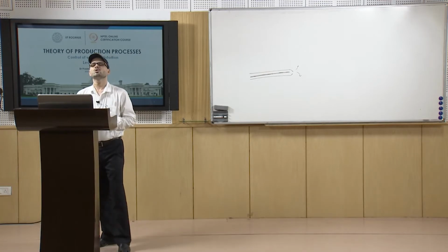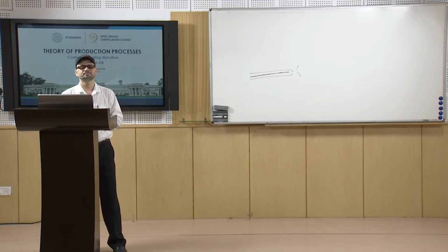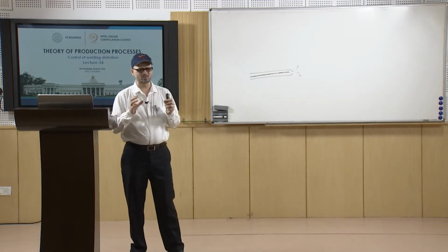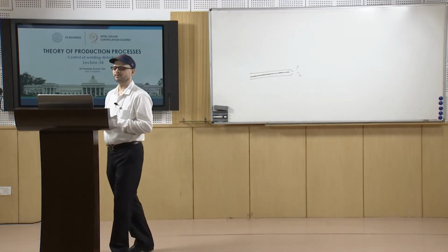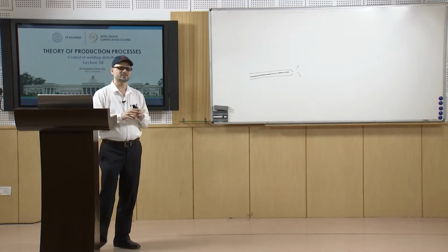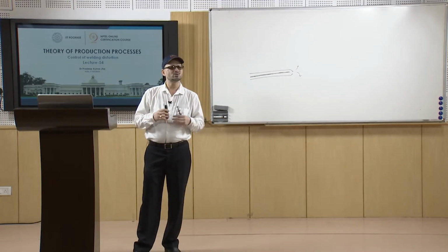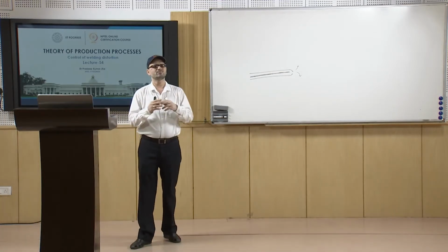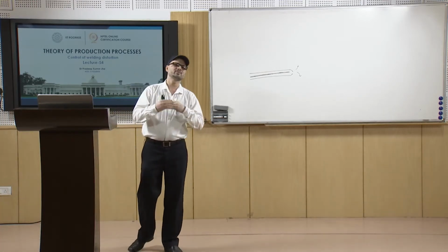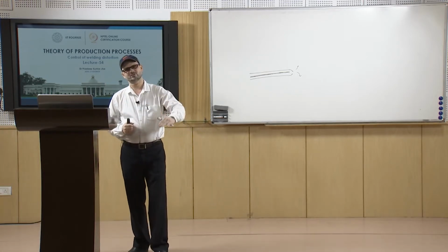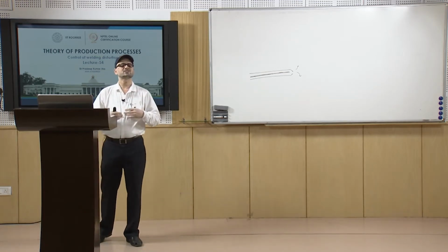That is why no excess metal should be deposited, and when you are making the weld deposit, the proper weld drawings should be followed, and there should not be any increase in the weld section, so that there is no increase in the weld metal deposited. So, if you have the minimum amount of weld metal deposited, which will suffice for the structure to be considerably strong, then that is better.